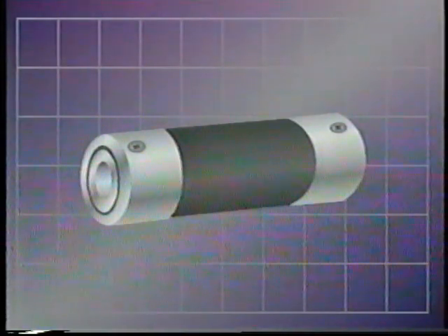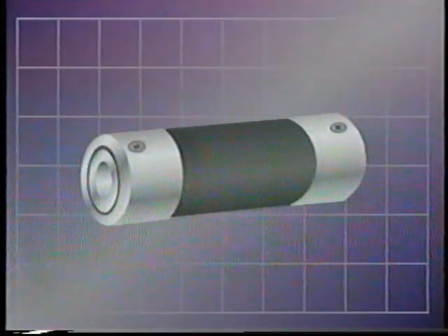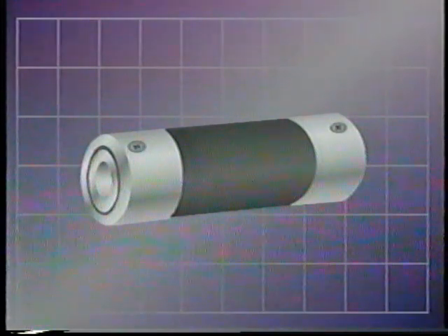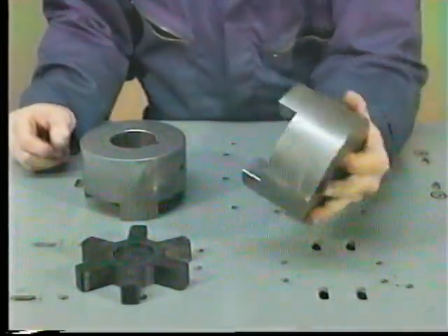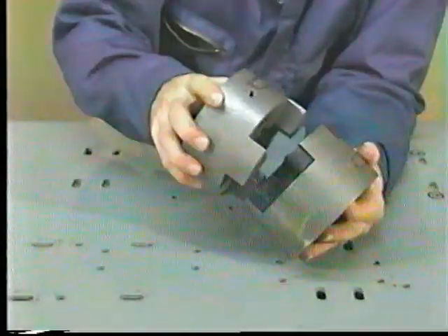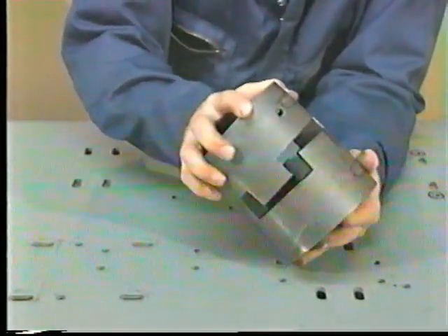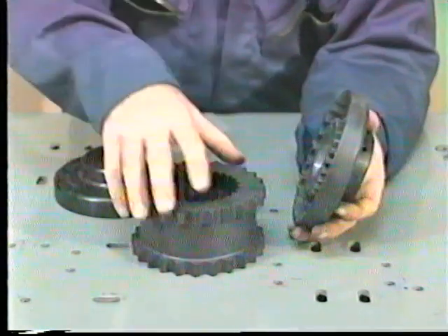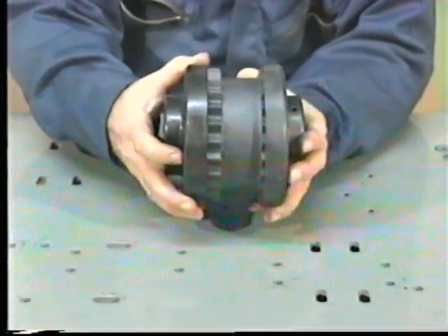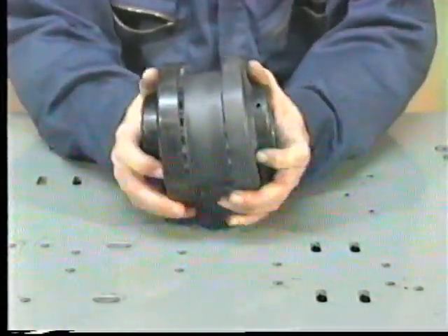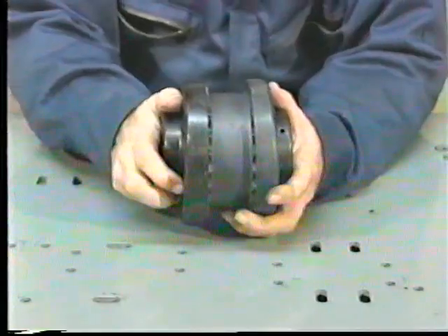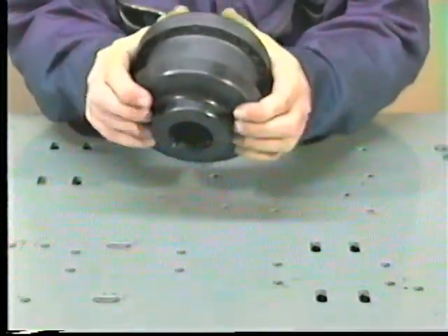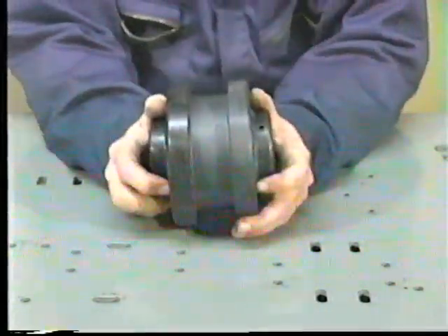For example, one very basic type uses a small piece of rubber hose which is clamped onto each shaft. Another kind of flexible coupling has a flexible rubber center disc which is inserted between the two coupling halves. A similar coupling has a continuous flexible center ring with notches that are plugged into each end of the coupling. Together, they make a flexible unit that can allow for as much as 2 or 3 degrees of misalignment. All the movement takes place in the rubber.